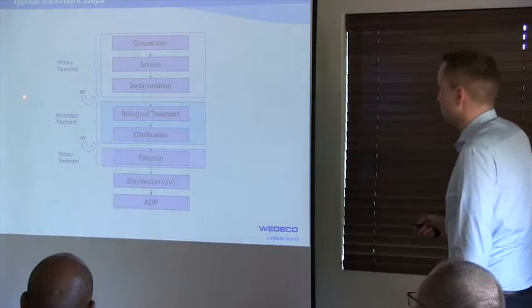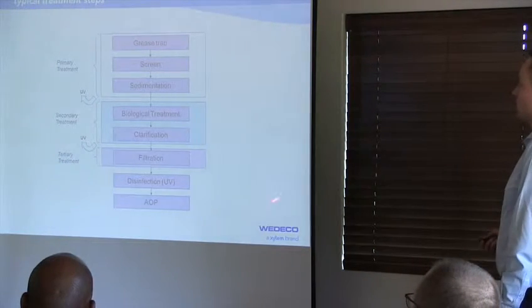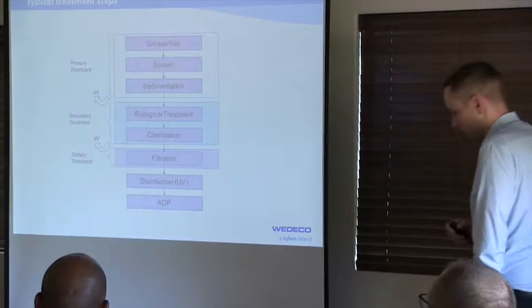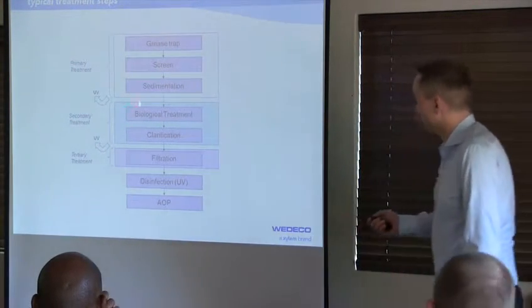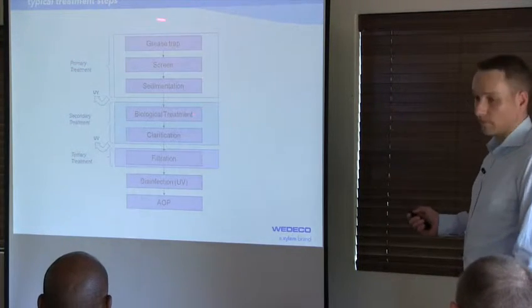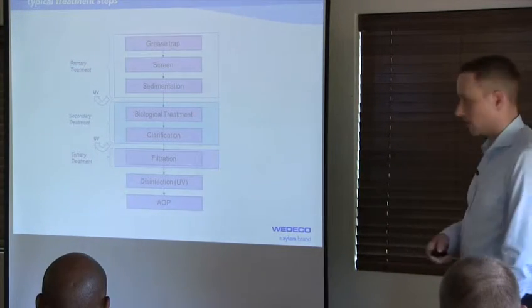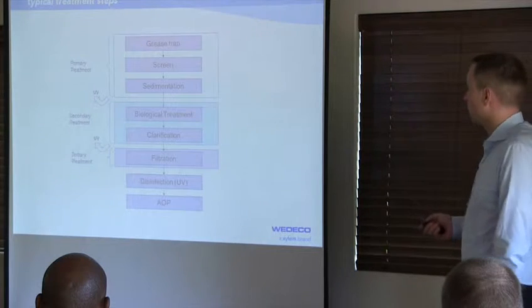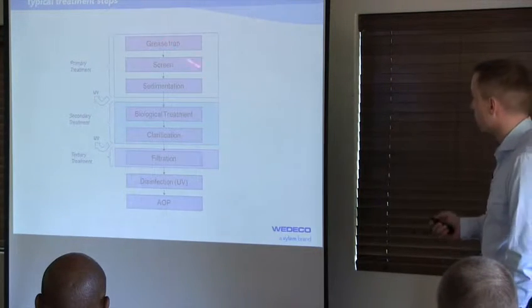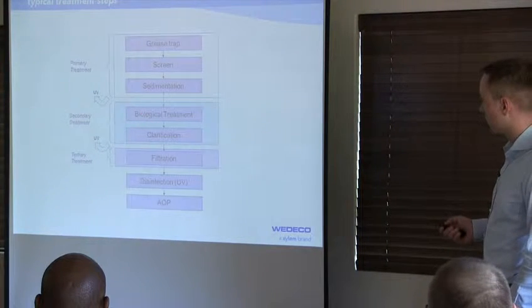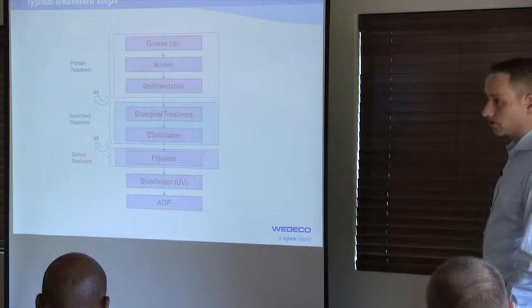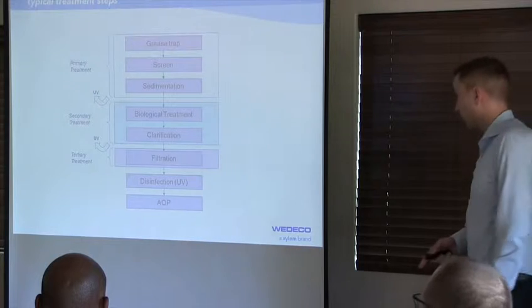For wastewater, we have UV depending on the local laws, basically. You could do it after a primary treatment only. In the UK we sometimes see that. That's not even a biological treatment, so you can set a UV system directly after sedimentation and then go to a direct discharge.